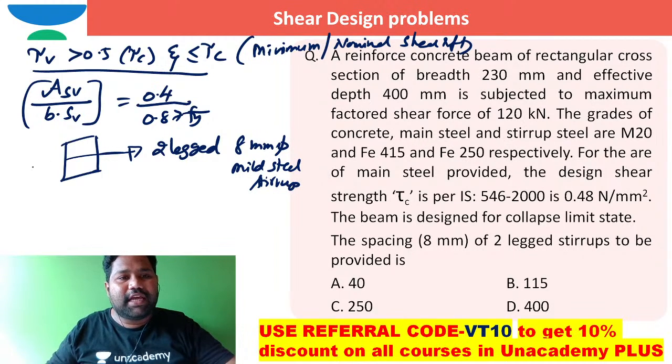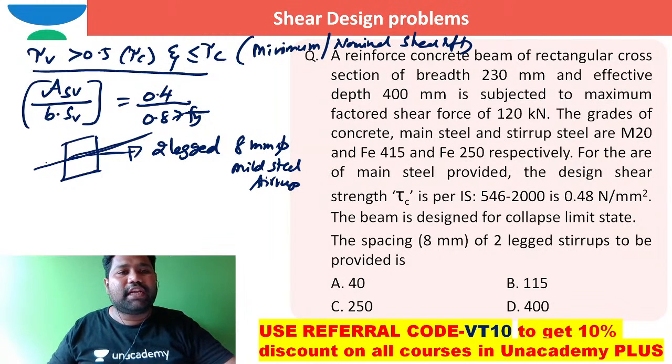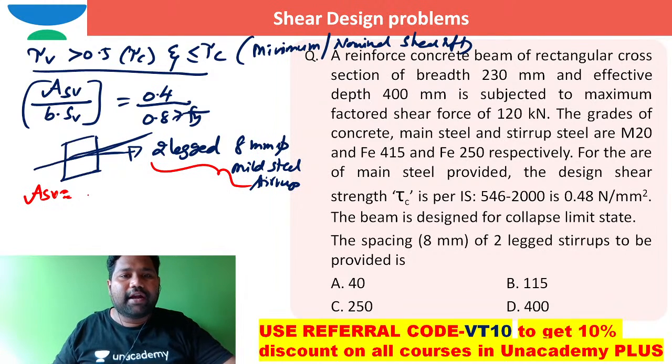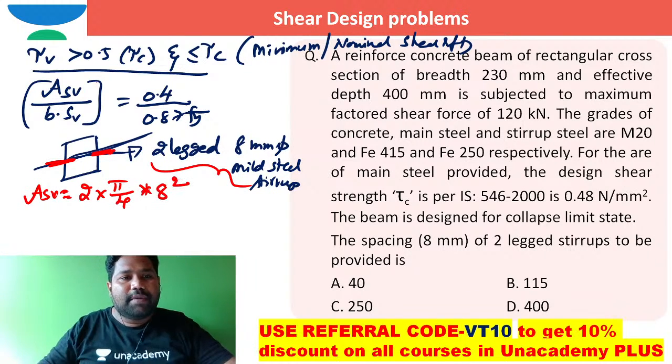Then the cross-sectional area of the two-legged mild steel 8 mm dia stirrups is known. What is Asv? Area of shear reinforcement. So what is the cross-sectional area Asv? If the example is two-legged 8 millimeter dia stirrups, there are two cross sections, so 2 into pi by 4 into 8 square. That means I know this.